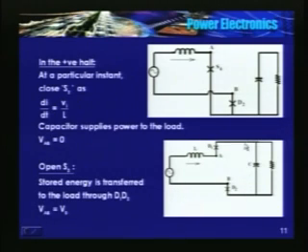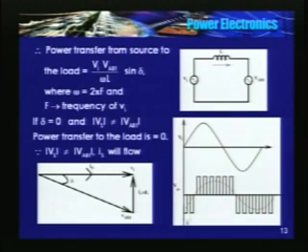So case 1, in the positive half we controlled S4, and in the negative half we controlled S2. So the waveform is 0 when the switch is on, and when the switch is off it is V0. By the way, the width of the pulse depends again on the control strategy. If it is a current control, maybe pulse width will continuously change.